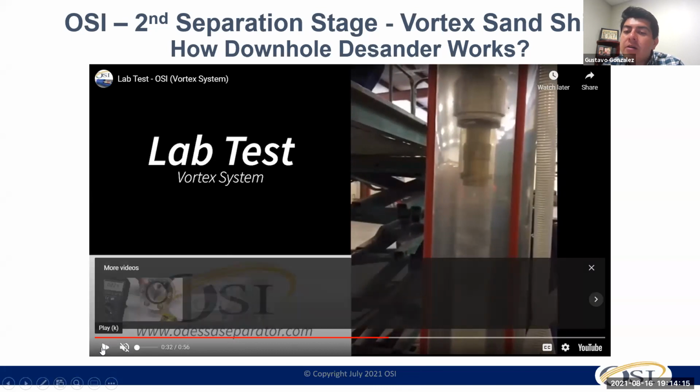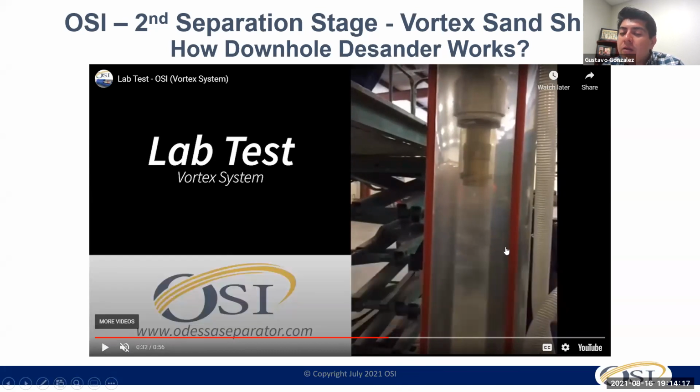What I was meaning earlier is that if I don't do the right calculation based on the sand volume or sand rate and the fluid production, my delta P is going to be so high that I can push this force 3 feet, 4 feet, 5 feet underneath it, and that amount of sand constantly hammering the ID of the tubing is going to start creating marks and sandblasting the internal components.